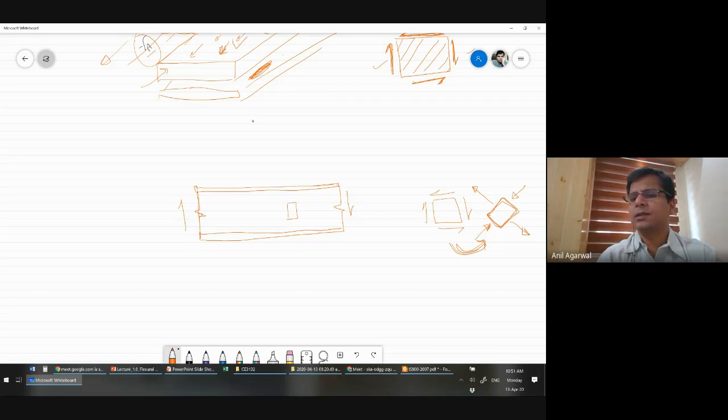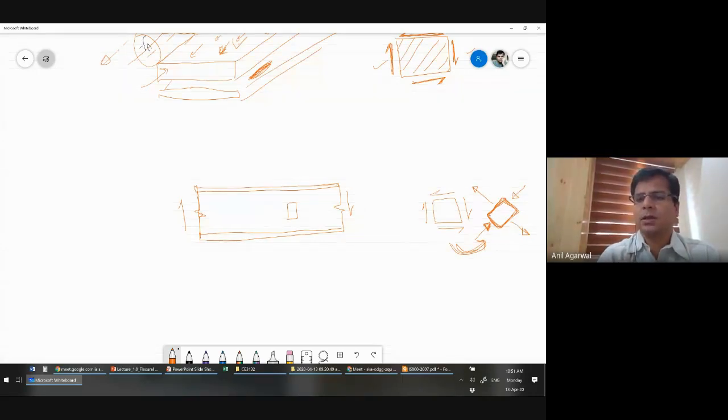Okay, and if you look at these stresses, you would notice that for this plate, there is one orientation where it is undergoing compression. Whenever it is undergoing compression, it may undergo buckling. So if the web is very thin, this plate will bend like this, right? What you will end up getting is somewhat like ripples of this kind.